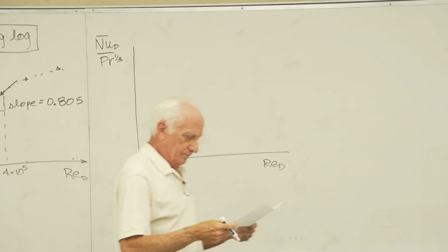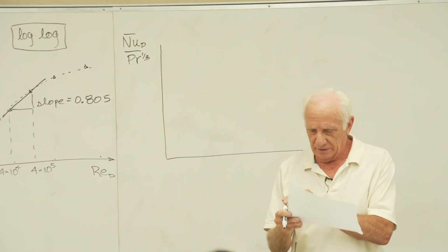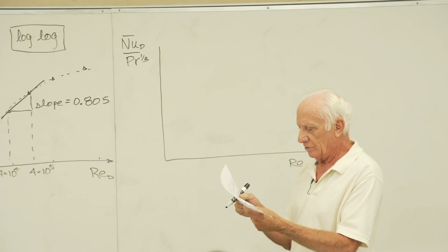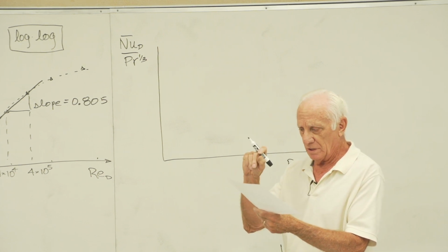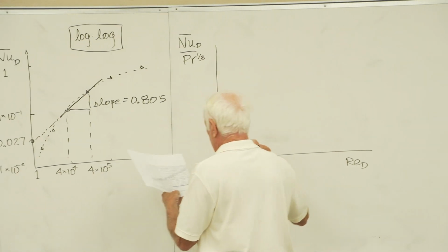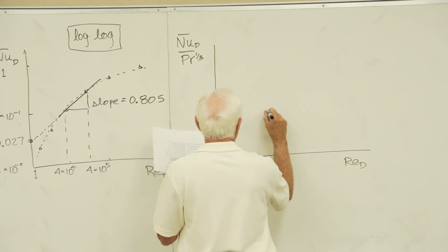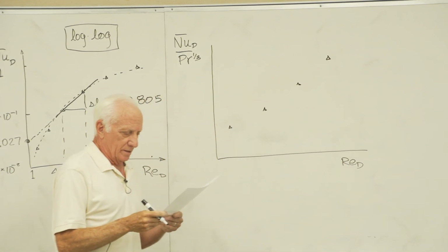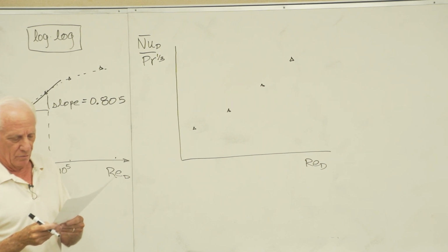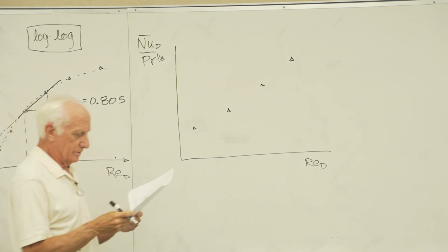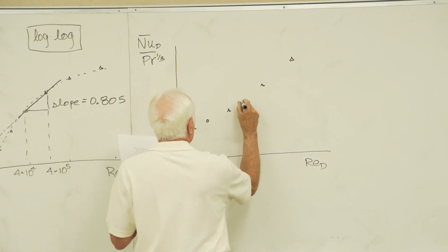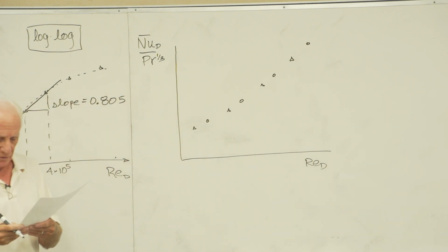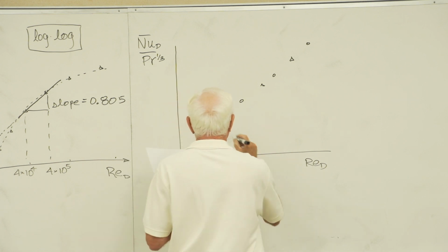Now, reference 19, those people experimentally used water with a diameter of the tube 0.0254 meters, which is 1 inch. 1 inch tube, water. They changed the velocity and they got these data points. Reference 20 used oil, diameter 1/10 to 2/10. So they got oil. That's oil. Then 2 other authors used air with different diameters. They got data that looked like this.